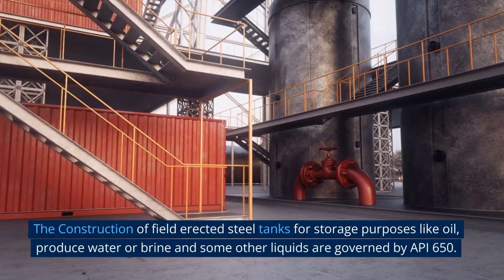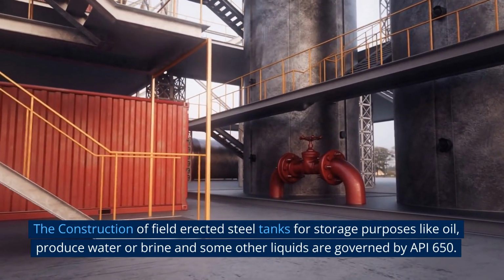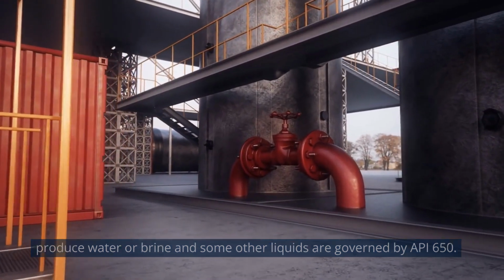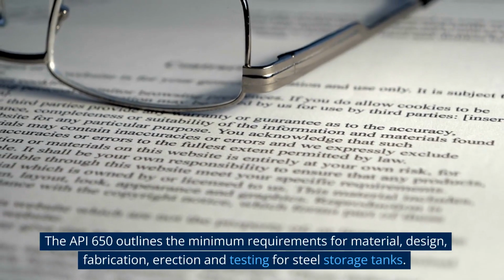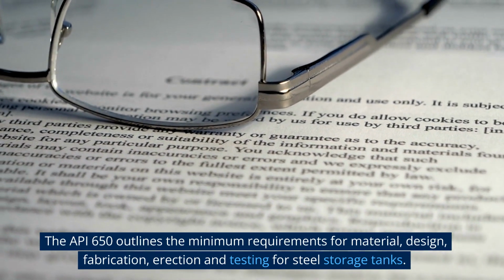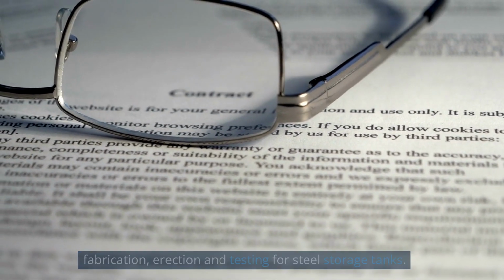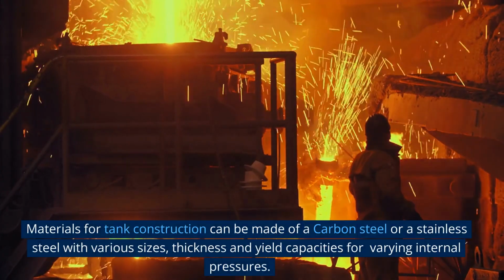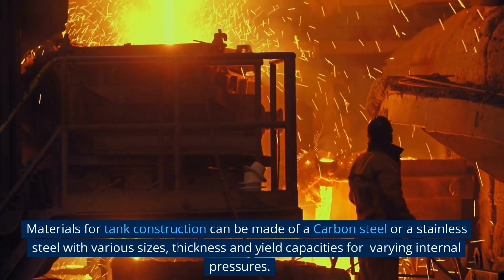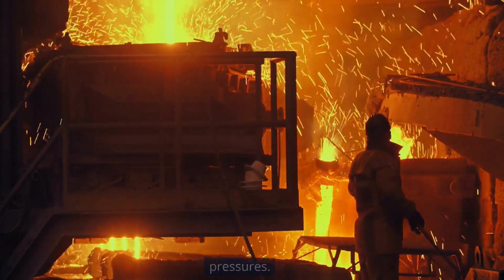The construction of field-erected steel tanks for storage purposes like oil, produced water or brine and some other liquids is governed by API 650. The API 650 outlines the minimum requirements for material, design, fabrication, erection and testing for steel storage tanks. Materials for tank construction can be made of carbon steel or stainless steel with various sizes, thickness and yield capacities for varying internal pressures.